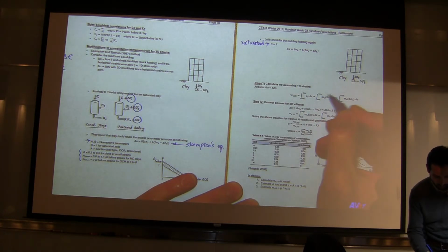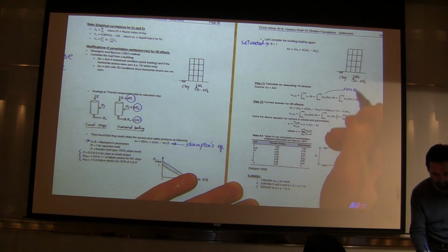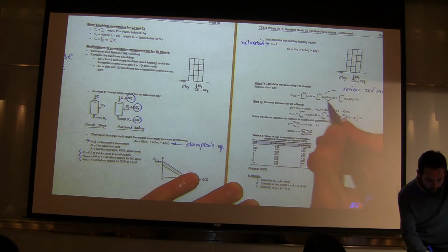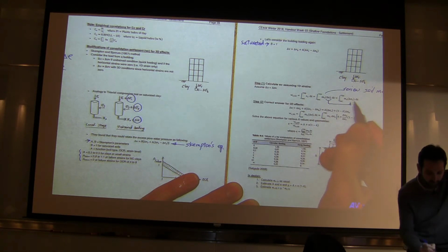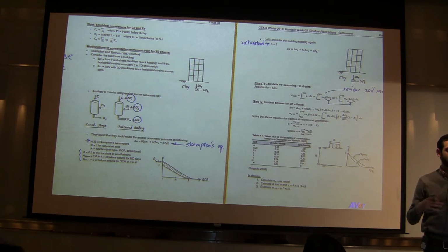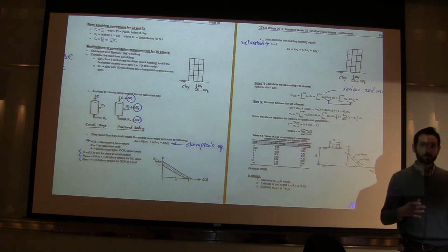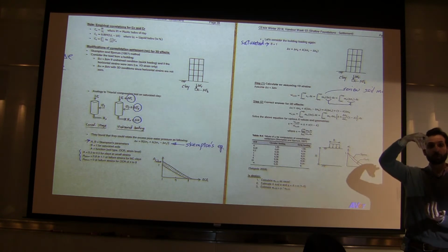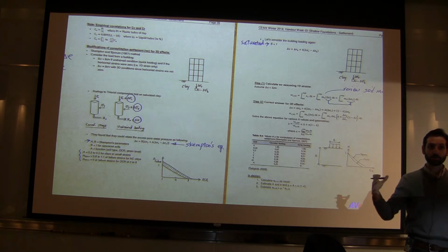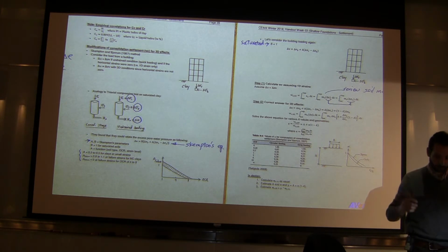So review soil mechanics. And you can replace delta U with delta sigma V, because every load that you apply vertically goes on water first and then transfers to the soil. This is a 1D case. In a 3D case, the load that you apply vertically does not go to water all the way. It goes to water and the horizontal stress.